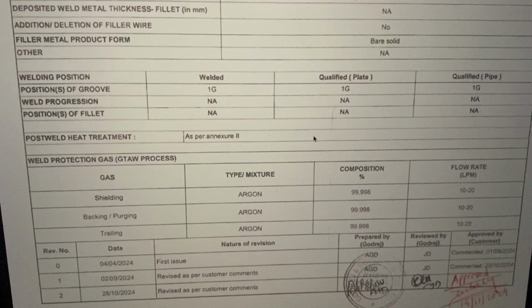how many places we introduced argon. See, these look to be very tedious and time consuming, and a WPS I would write in 15 minutes, the way I am elaborating here, may take 3 hours, 4 hours, or sometimes even 2 days. But you will realize it once you go onto the shop floor, if you don't specify and make it mandatory. Because once you write in the WPS, whether supplementary, essential, or non-essential variables, all of them are going to become essential.